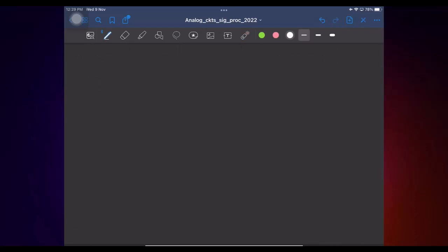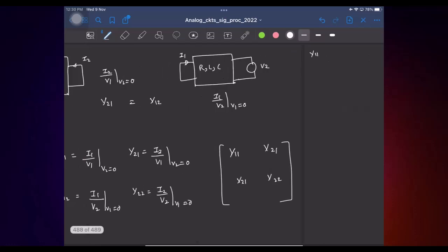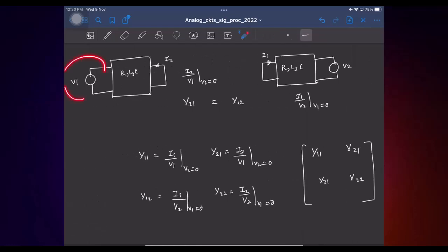And let us say you have some small subsystem made into an IC. You want to characterize its Y parameters. So what will you do? You will basically try to put it on a PCB, and let's say these are the 2 ports. Let's say you want to find Y11. What do you have to do? Apply the input on port 1, short the port 2, and measure the current flowing in the second port.